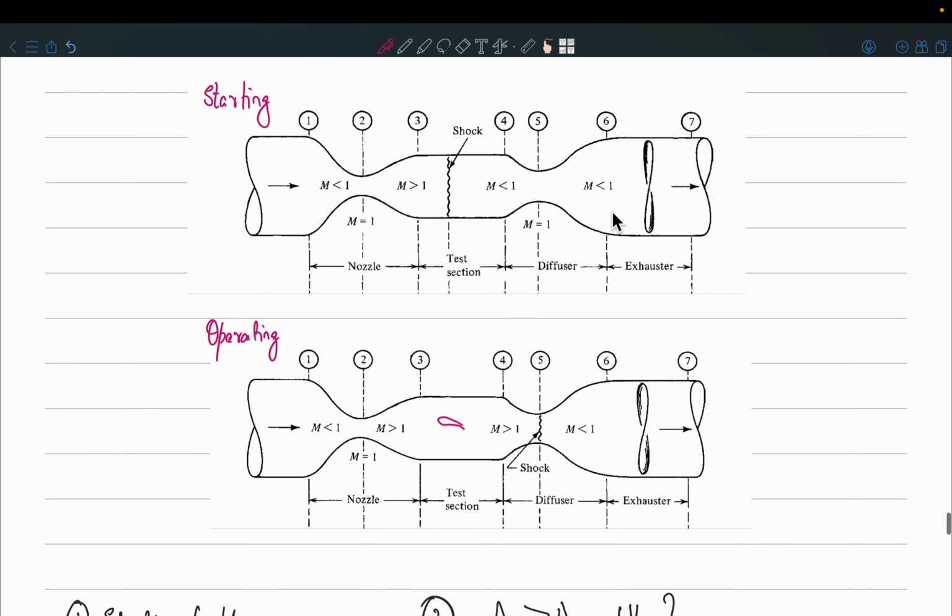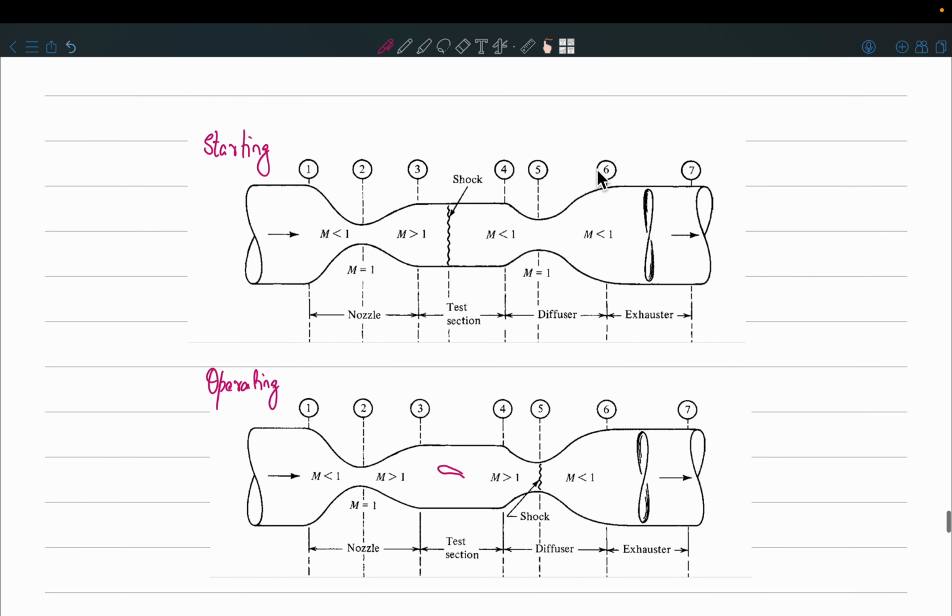Okay, so when the flow moves at very high speeds, if you start decreasing pressure, first it will be subsonic throughout, but as you decrease the pressure further and further, if you remember that particular diagram where we said that the receiver pressure or the pressure ratio determines whether you are operating at first critical or second critical or third critical or somewhere in between. So basically when you come out of the Venturi regime, then you remember the Venturi regime, right? Then as soon as you cross the first critical point, you will start getting shocks.